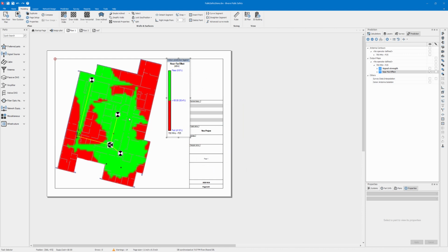So you can take a look and see that you have some weak regions that might need maybe an extra antenna, or maybe simply moving this antenna around could fix it. Up to the designer. Same thing about floor 2, it's identical to floor 1. And this sums it up for the near-far effect map. Now let's take a look at the Uplink AGC map.